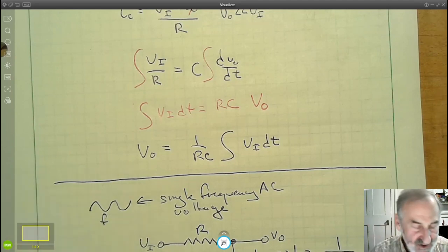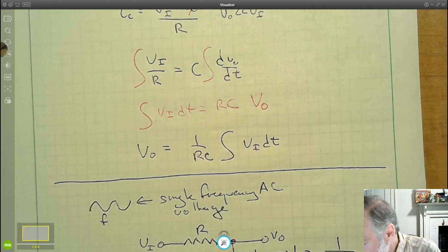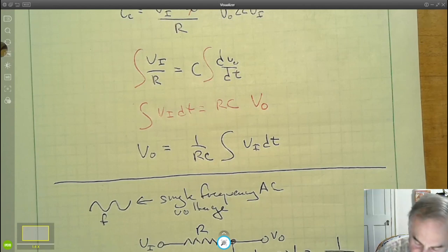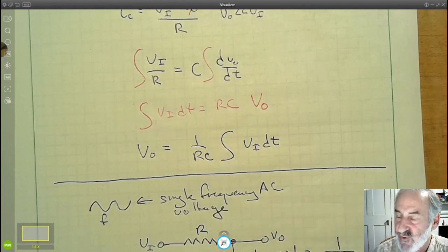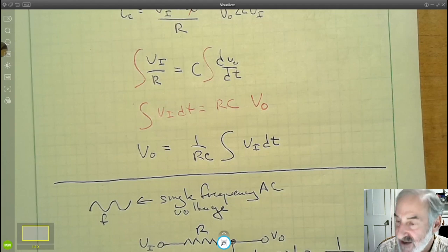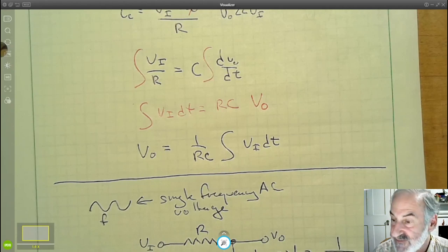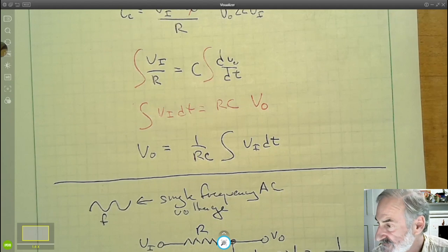And we're not going to do much more worrying about the frequency response of capacitors, but the thing I want you to remember is that at high frequency, the capacitor is a short circuit, and at low frequency, it's an open circuit. And so if it's teamed with another element like a resistor, it creates a frequency-dependent voltage divider.